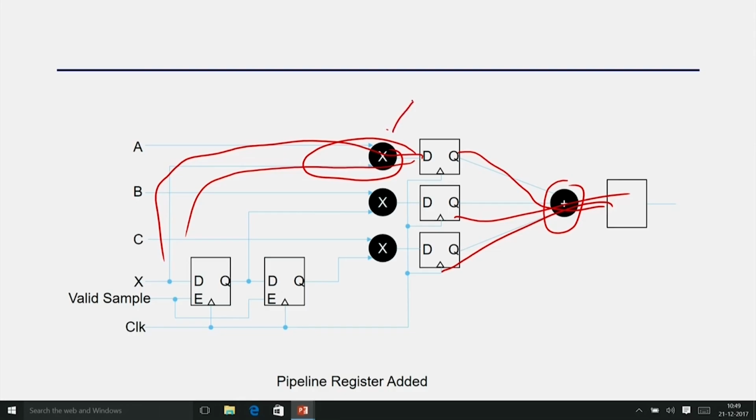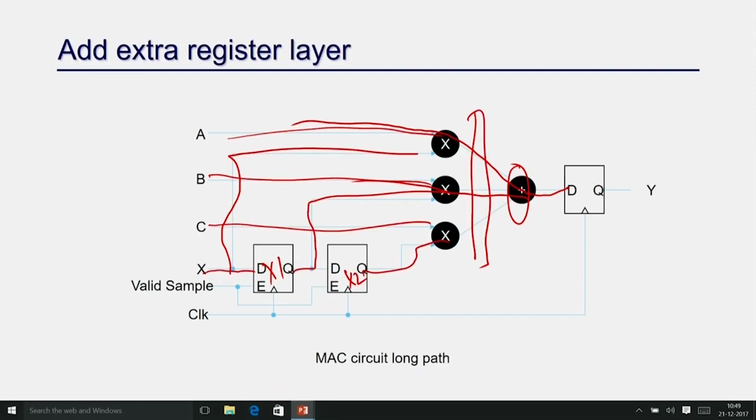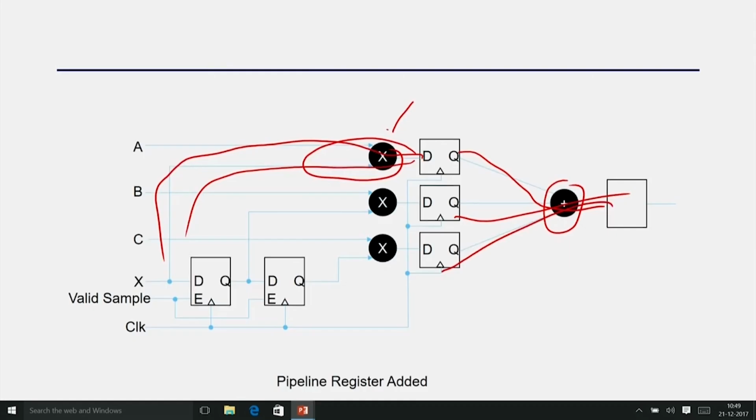Okay. So you can understand here that if you just add a register, your latency will be increased by 1, right. But that has to be taken care of. You are not changing your functionality, but you have to synchronize your design with other components, since your data will come after 1 extra cycle. Earlier if it was coming after 5 cycles, now it is going to take 6 cycles to compute, because I am just adding one extra layer, right. So you have to take care of that factor, so that you can synchronize this part of your design with the other components of your design.